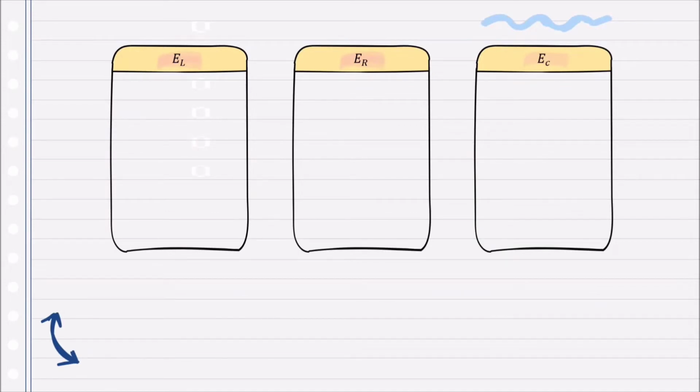Firstly, let us refer to Faraday's law and Lenz's law. It states that the voltage drop across an inductor is directly proportional to the rate of change of current, with proportionality constant L. Hence, we obtain our E_L. Secondly, Ohm's law states that the drop of voltage across a resistor corresponds to the current flowing through the resistor in the circuit, with constant of proportionality R. Hence, we get our E_R. Last but not least, for any given capacitor, the charge Q is directly proportional to the capacitance C and the voltage across the capacitor. When we rearrange the equation, we obtain E_C equals Q over C.